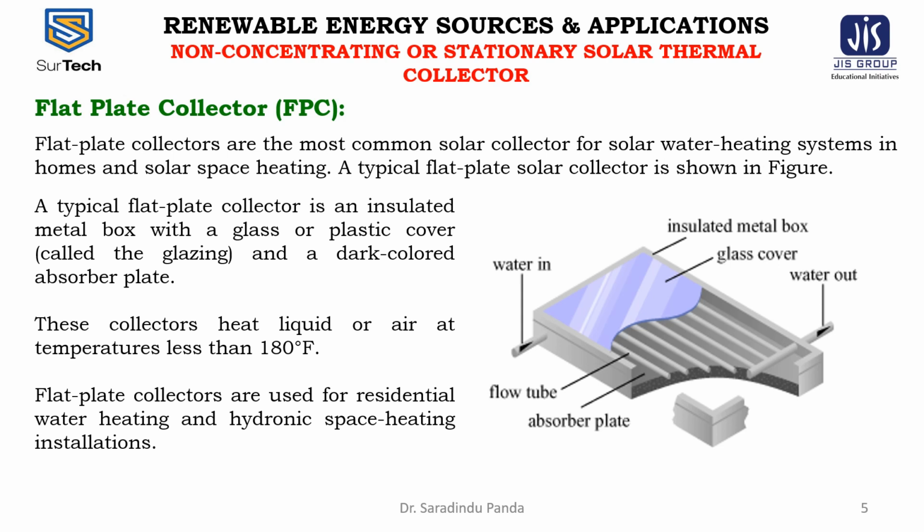When the solar radiation passes through a transparent cover and impinges on the blackened absorber surface of high absorptivity, a large portion of this energy is absorbed by the plate and then transferred to the transport medium in the fluid or air tubes, to be carried away for storage or use.